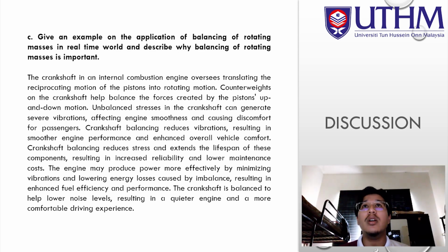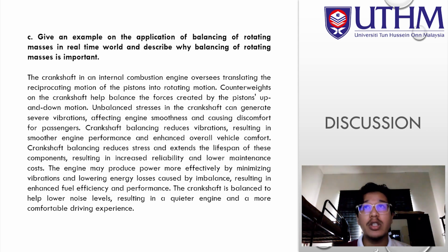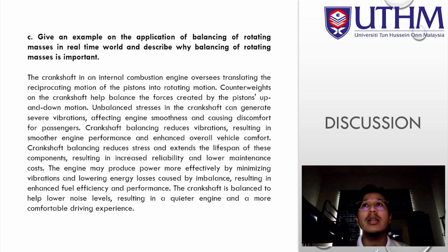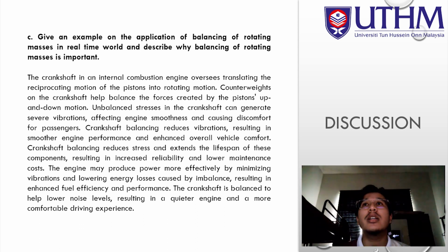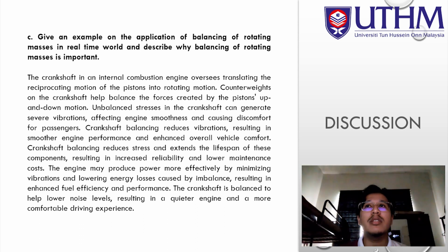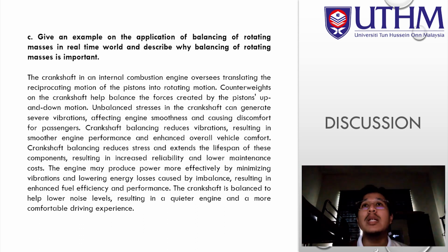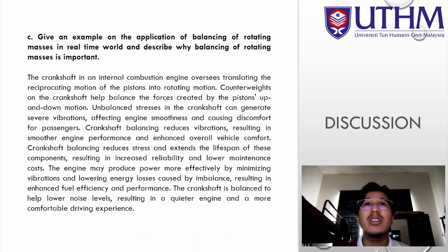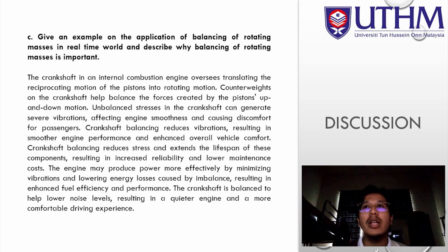Next is to give an example of the application of balancing of rotation in the real world and describe why balancing of rotating masses is important. The crankshaft in an internal combustion engine is responsible for translating the reciprocating motion of the piston into rotational motion. Shaft balancing reduces vibration, resulting in smoother engine performance and enhanced overall vehicle comfort. Crankshaft balancing reduces stress and extends the lifespan of this component, resulting in increased reliability and lower maintenance costs.